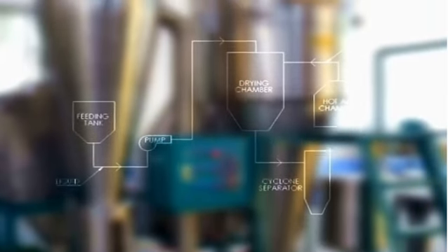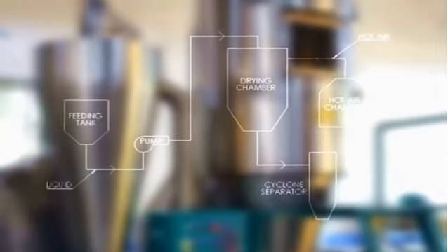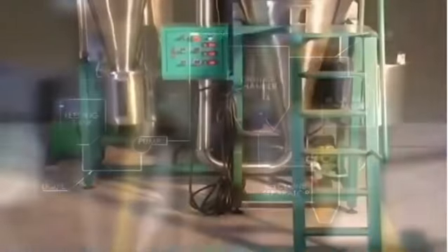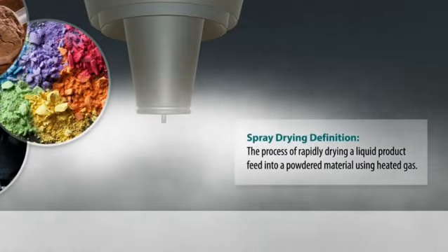The principle of spray drying is based on rapid evaporation of moisture from tiny liquid droplets using hot air. Essentially, when a liquid is broken into very fine droplets, it has a very large surface area. This allows moisture to evaporate almost instantly when exposed to hot air, leaving behind dry powder. This process combines the principles of heat transfer and mass transfer.